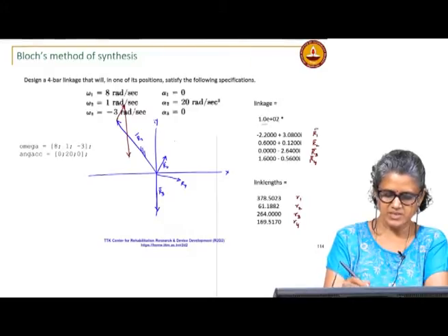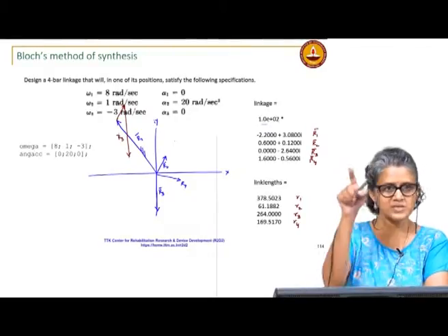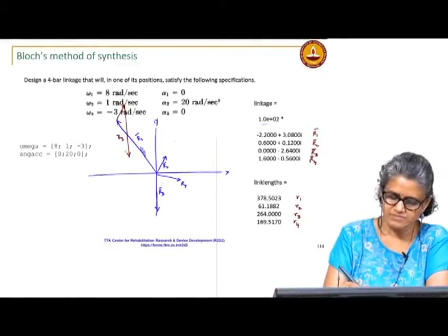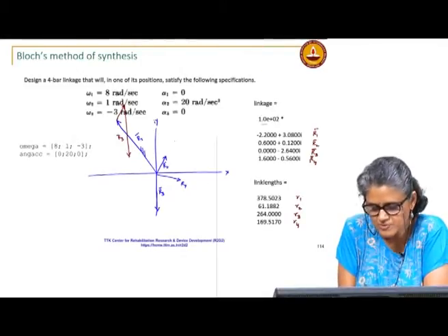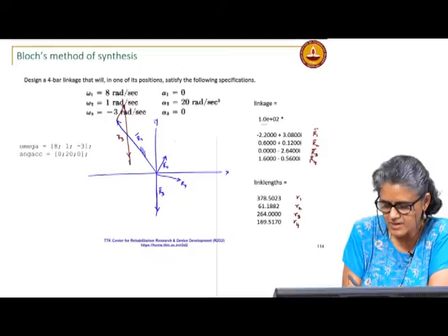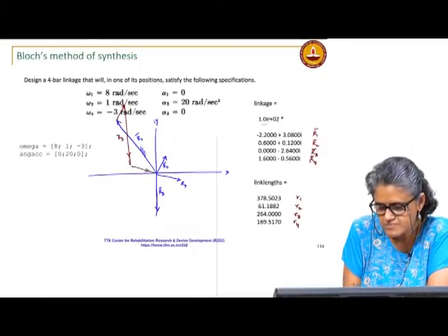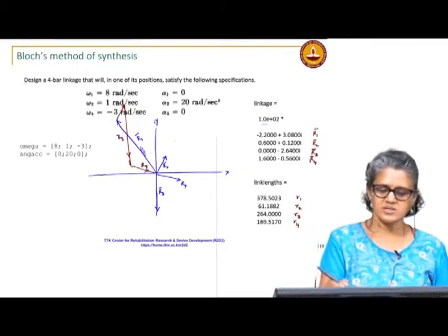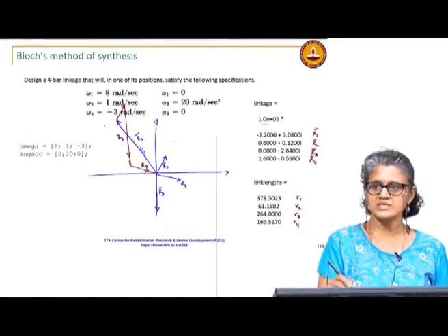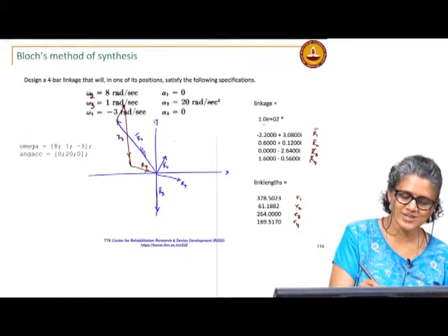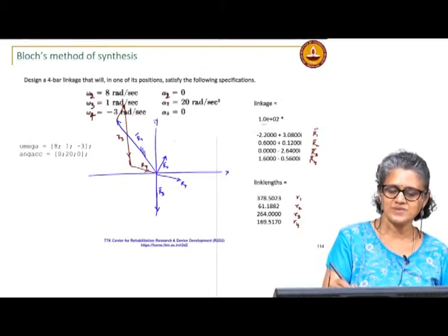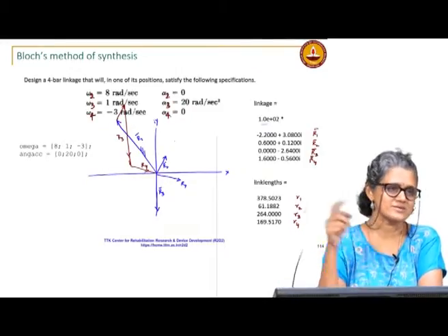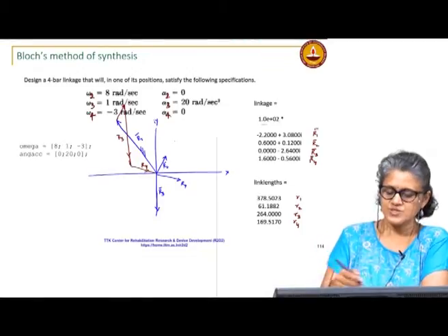Okay. So, this is my R 3, because I have to satisfy my loop closure equation, R 1 plus R 2 plus R 3, then okay, this should be R 4, they should be parallel to this, but yeah. So, this is R 4. So, this is my linkage. Okay, the book uses a different notation, sorry, alpha 2, alpha 3, alpha 4. The book uses 1 for the input link and uses 4 for the fixed link. So, this becomes your linkage.